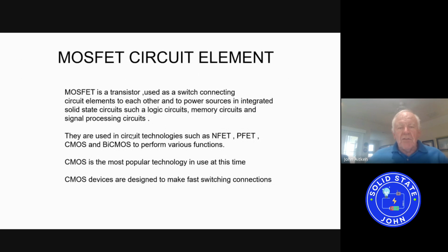The MOSFET's a transistor, and it's used as a switch to connect circuit elements to each other and to power sources in integrated solid-state circuits, such as logic circuits, memory circuits, and signal processing circuits. They're used in circuit technologies such as NFET, PFET, CMOS, and BiCMOS technologies to perform various functions. CMOS is the most popular technology in use at this time.